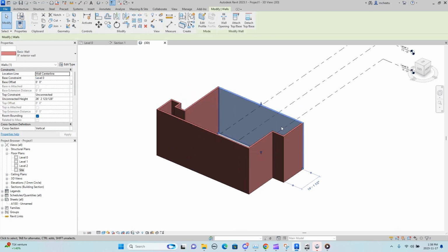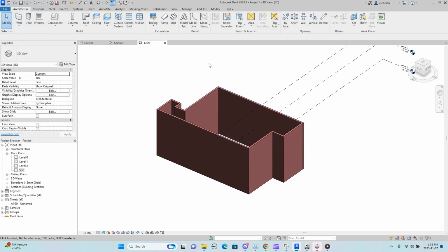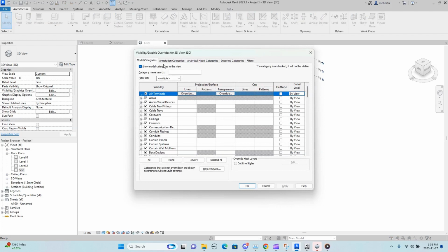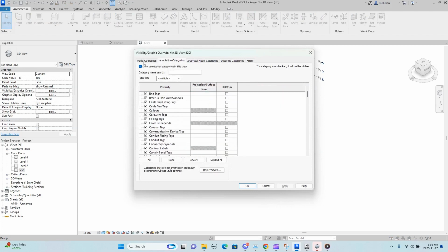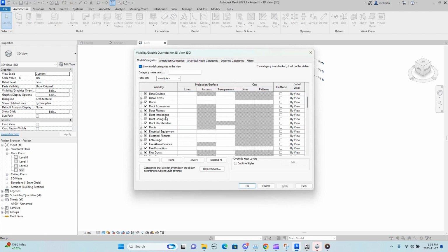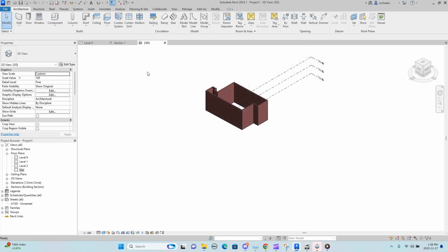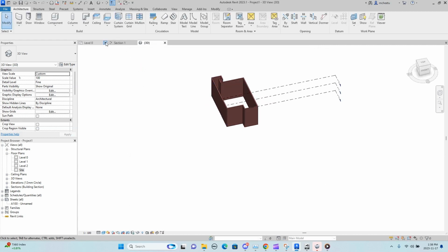Here you go. I'm gonna show you how you can control all the view properties without hiding it. You can also take off the CAD file in the view properties. If you come here, you have all the options which you want to turn off and turn on. So here is our CAD file. You can turn it on and off. I'll show you later, but this is just a basic video. We'll just get along and find out the new options, how to do things and all that stuff, right?